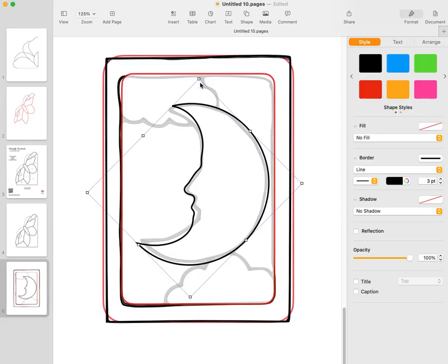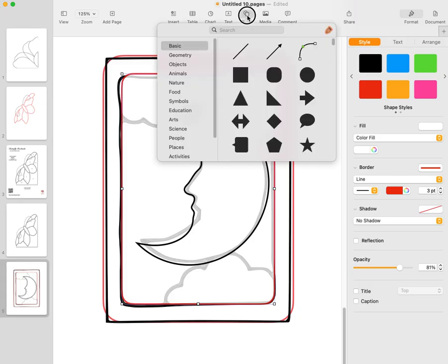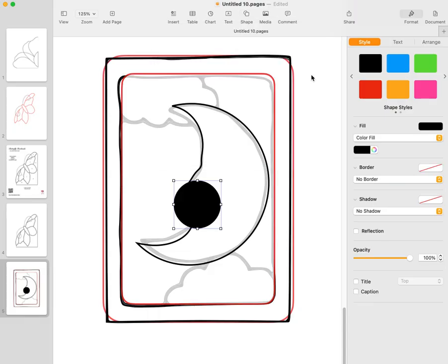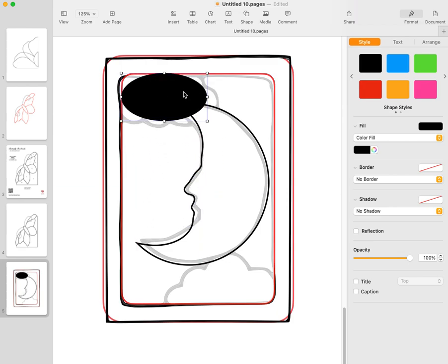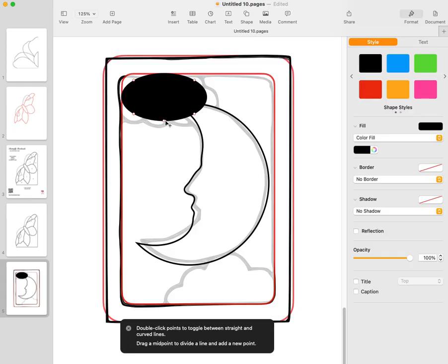And next, say you want to do a cloud. Alright. You can go back to a circle. Bring it up like that. And left mouse click, make editable. Now here, what I'm doing is keeping this black so I can see it. You see how I pulled this circle? This waypoint is in the shape of a circle. So that's telling you it's a curved line. Alright? You double click it, it makes it a point. Alright? So you wanted a point.